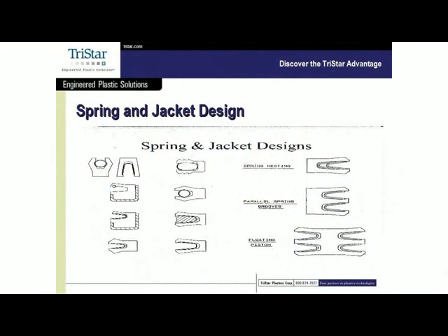This is just a view of some of the different designs. We even have a picture there of some can seals utilizing both helical and V-spring or cantilevered beam springs. Cantilevered beam springs with RTV fillers for FDA applications or sanitation applications. Multi-lip springs, nested springs. You can see just a big variety of both the spring and jacket designs here.